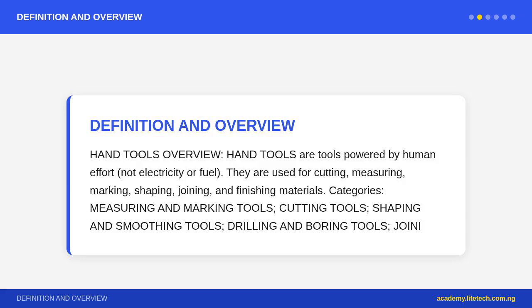Hacksaw, a metal frame saw with a replaceable blade, used to cut metal, pipes, rods, bars. Teeth point forward, cuts on the push stroke. Chisel, a sharp steel blade with a handle, used to cut, pare, or chop wood. Types: firmer chisel, general use; mortise chisel, heavy duty for cutting mortise joints. Always keep chisels sharp, always cut away from the body.